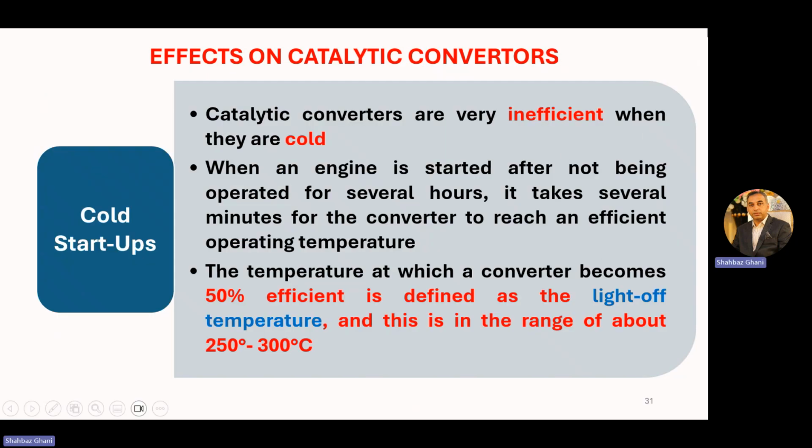Now, cold startup effects on the catalytic converter. Catalytic converters are very inefficient when they are cold. Normally, a cold catalytic converter does not convert the emissions to water vapor and carbon dioxide, because it is very inefficient at cold temperatures. When an engine is started after not being operated for several hours, it takes several minutes for the converter to reach an efficient operating temperature.